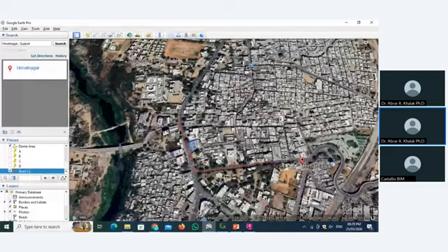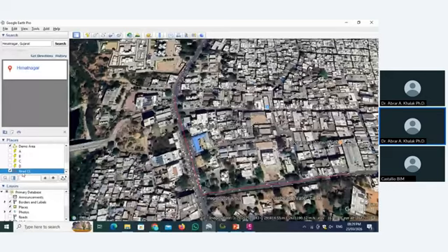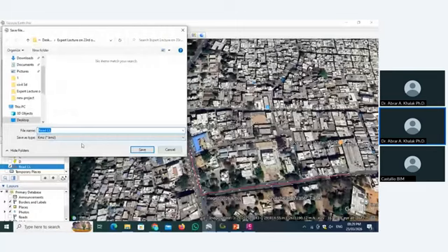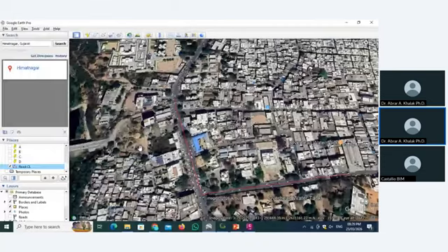So we have this one mark named road center line. Now we save this road center line. Go here to save places. Now remember, whatever file we save from Google Earth is in KMZ format. So the file name is road center line, and I save this in today's lecture folder with the name road center line. Save, done.